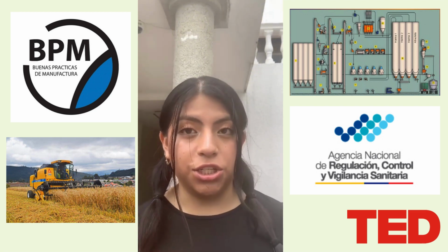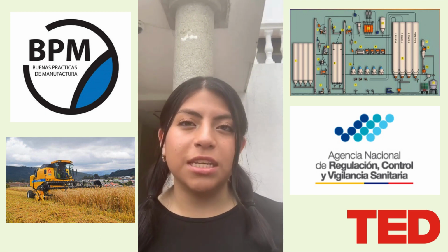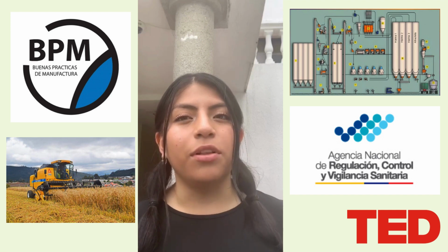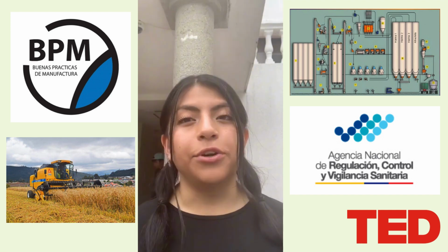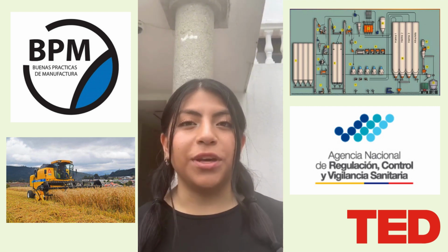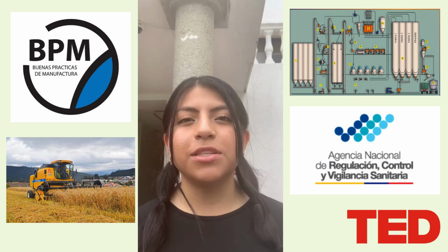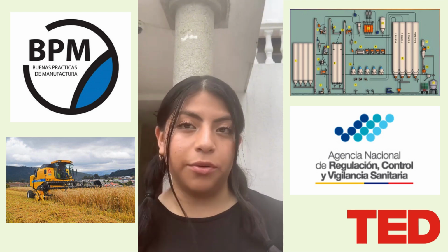Third, conditioning. Wheat is conditioned by adjusting moisture and temperature to facilitate milling. This may involve a modification or drying of the wheat as needed. Fourth, milling. Cleaned, conditioned wheat is ground to produce flour. The milling process may involve various steps such as crushing, separation, and sieving to obtain different types of flour.